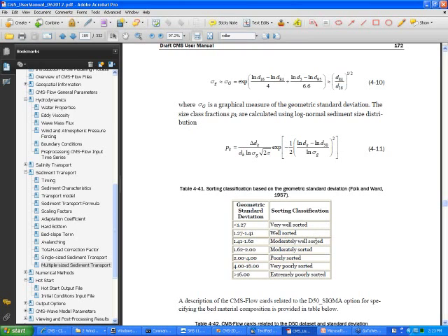For coastal areas, we rarely get into the range above 4. You know, even like 3 or 2. Most of the time, coastal sediments are moderately sorted or better. You know, I haven't seen cases where it's extremely poorly sorted or very poorly sorted.